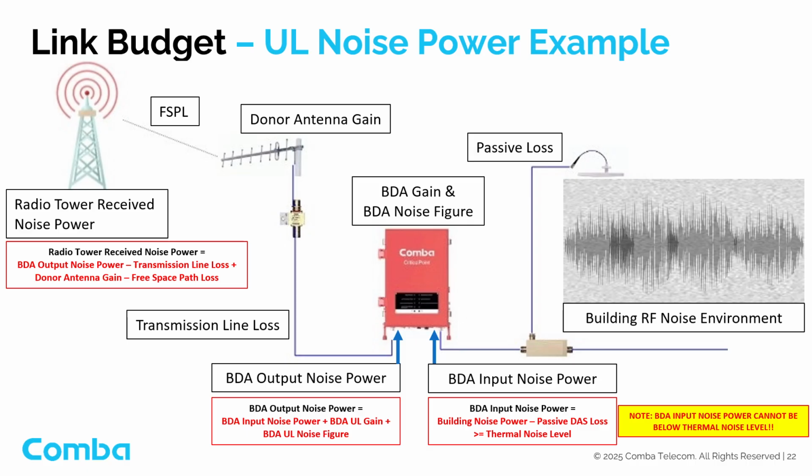In this calculation, it's important to recognize that the resulting value may sometimes fall below the thermal noise floor. While the actual noise level cannot be lower than thermal noise, we present the theoretical value to illustrate the margin or headroom relative to that limit.